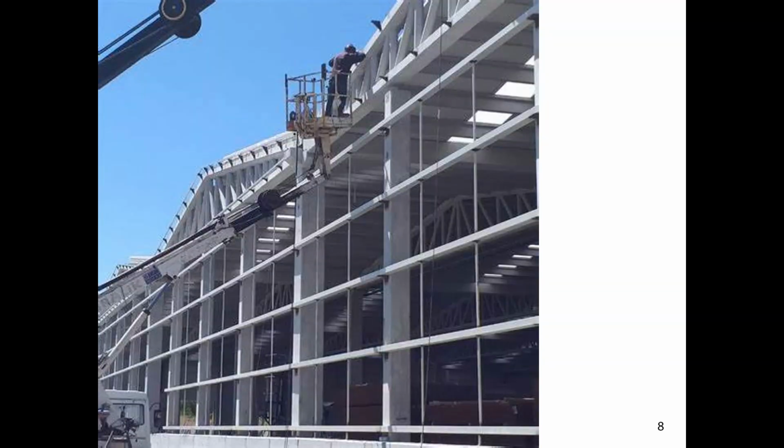Another situation which might make a little bit more sense for us, we've got perhaps a structure. This is maybe the face of a building. And these are little members, they're called girts. Basically what they're there for is to support some glass glazing. And so these columns that are responsible for carrying the gravity load from the roof, they're also going to be carrying point loads, which are the reactions from these girt members. If there's wind blowing on that wall, there's going to be some bending applied.